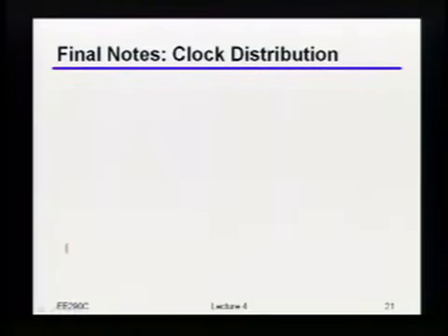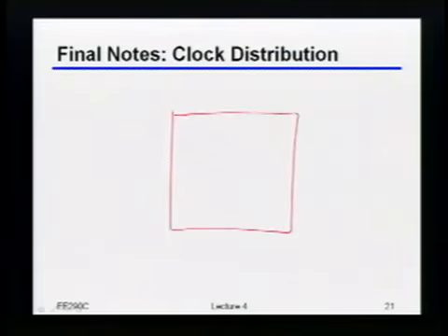Because you can imagine you've got some big chip, as an example, a microprocessor or something like that. You've got all the links distributed on one side over there. Well, this side over here could easily be on the order of 10, even 15 or maybe 20 millimeters on a side or so. If you think about that, I probably don't want 10 different crystal references out on the board for all of my links. So there's probably just one little crystal coming in somewhere, maybe on the bottom side of the chip.